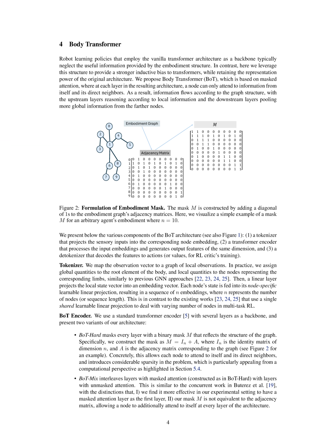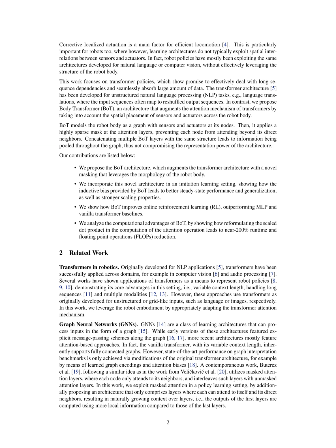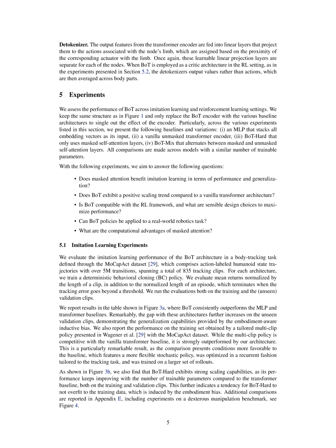In contrast, BOT incorporates a masked attention mechanism that allows each node, representing sensors and actuators, to attend only to itself and its direct neighbors, effectively modeling the robot body as a graph. This design enhances the inductive bias for policy learning, resulting in improved steady-state performance, generalization, and computational efficiency compared to standard architectures. By addressing the limitations of previous approaches, BOT demonstrates superior performance in both imitation and reinforcement learning settings,